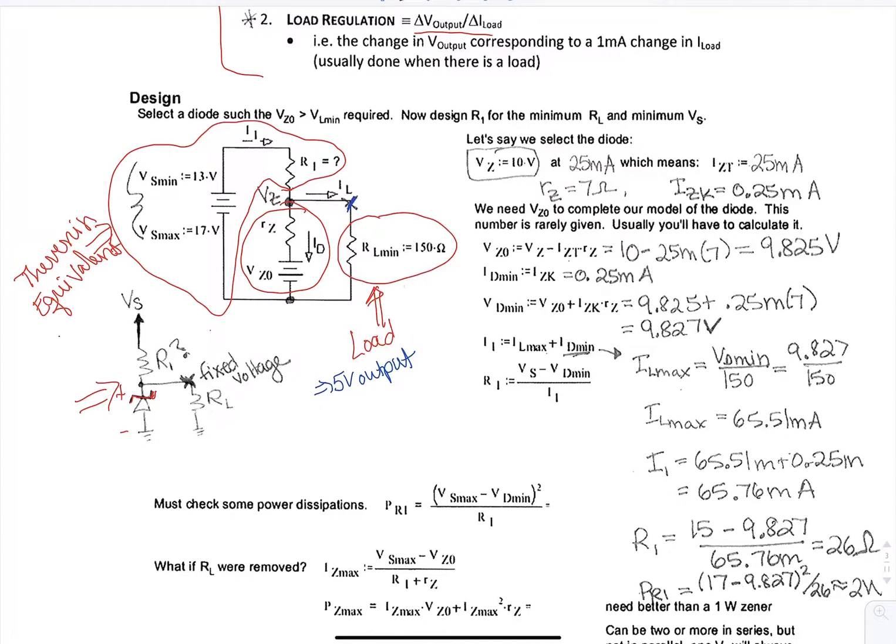If at this node you want to keep 5 volts out, and you know you also need to be able to pull through this 100 milliamps, you can model that by an RL of your voltage over current using Ohm's law. So that's going to be 5 over 100 milli. That will give you your value of what you want to use for your RL value.